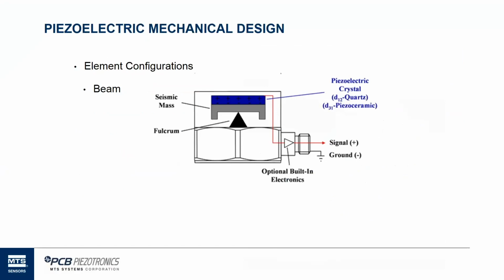So that's our inertial mass, and you see we have weights out to the side to make it more likely to flex. And we bond that to the crystal that's finally on the top, and that gives us the ability to do surface strain on the top and bottom. The surface strain causes electrical polarization on the top and the bottom of the device. And those two sides of the crystal are once again routed to an op amp and then routed outside of the accelerometer on a 2-wire interface. This is a very high output design. It's very low mass too, because we don't use a lot of tungsten in this design, almost none.